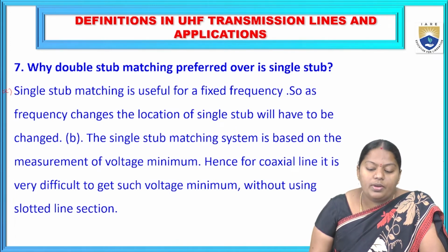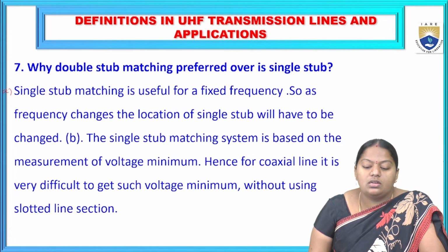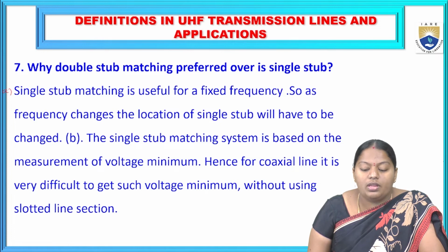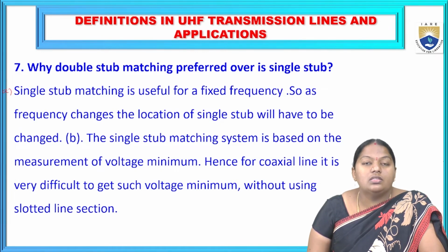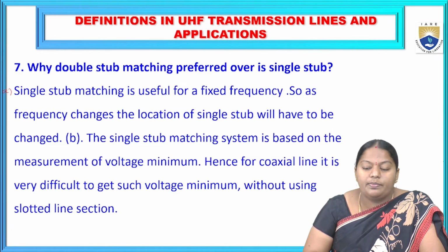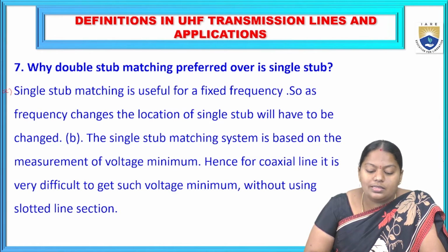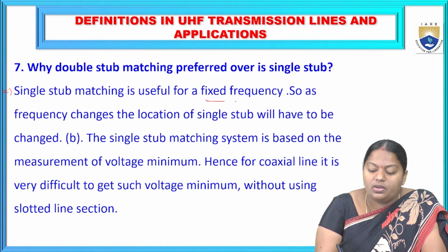Okay, so the drawback which exists in single stub matching is that it is applicable only for fixed frequencies. If you want to go for variable frequencies, then we consider a second type of stub matching technique called double stub matching. So single stub matching is useful for a fixed frequency.